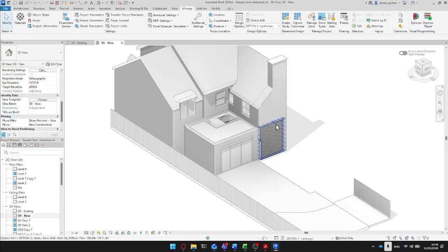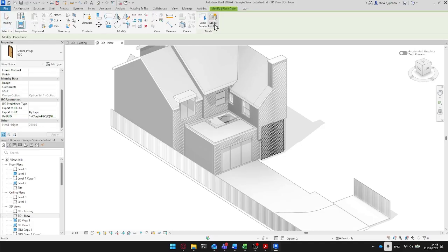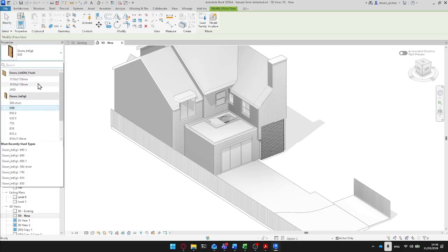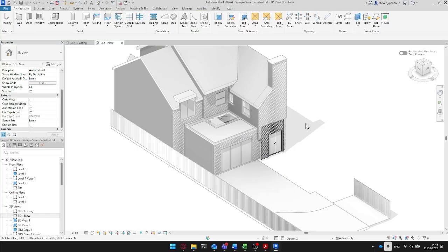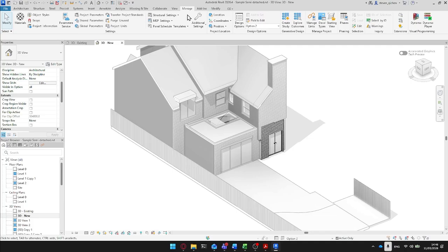But we can now see that if we delete this from one of the design sets, when you switch between the design options, it changes. So, in this case, we might as well leave that wall out in one option. In one option it's just an opening, and in the other option we'll do a double door. So again, you can see here we've got two design options, 1 and 2.